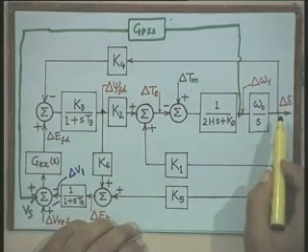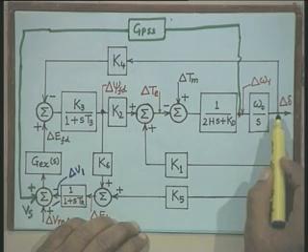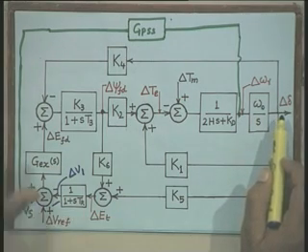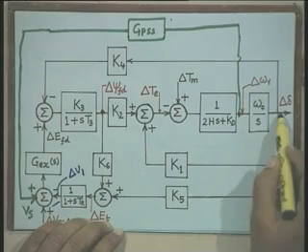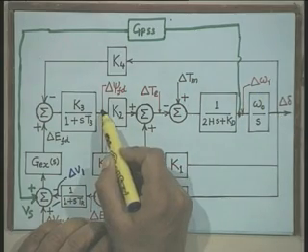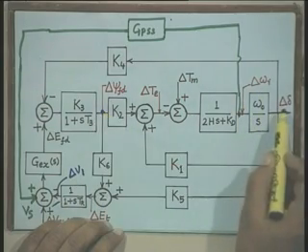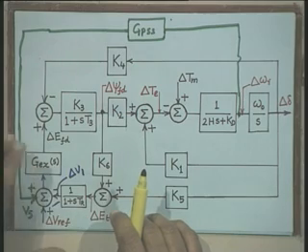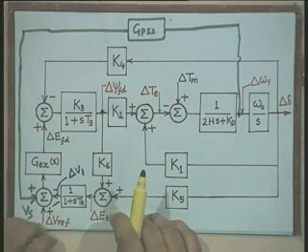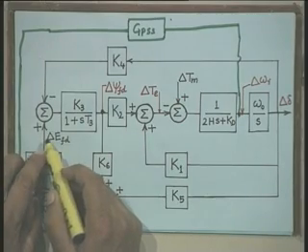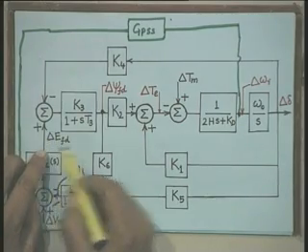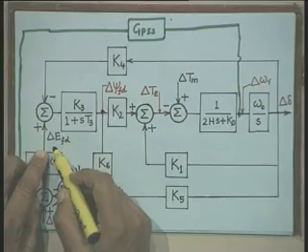Therefore, the state variables required to model the system in state space form are delta omega r, delta delta and delta psi FD. With these 3 state variables, one can write down the state space model of the system, and the input to this model will be delta Tm and delta EFD.